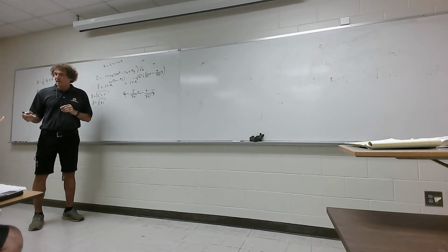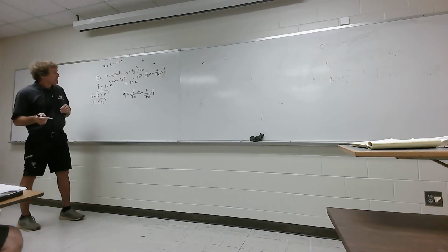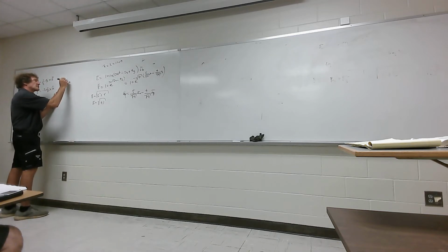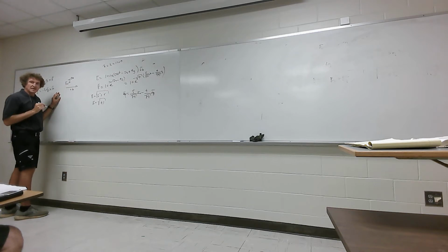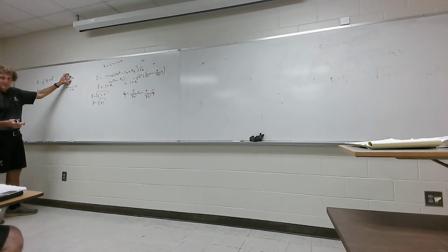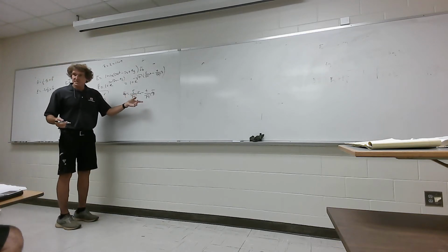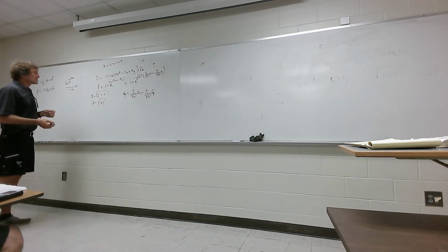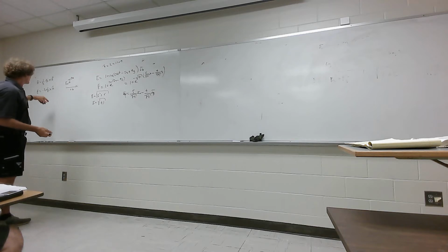Can you explain why you factored out the minus 1 in the exponent? Remember, in general, if you have E naught e to the minus j beta z, that's a wave traveling in the plus z direction. To get the unit vector, I need the direction it's traveling, so I make sure I have a minus j there, and then I pull out the beta terms. But anyway, you can get the fractional values of these. Do you follow me on this? And that is a unit vector. Now that unit vector is what you use to get the H field from that equation.